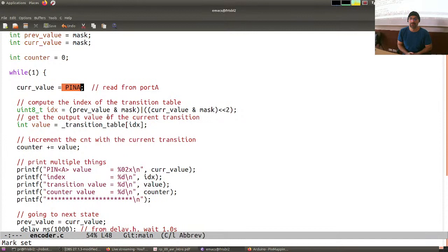Now, I don't like it because it involves a lot of ifs and a lot of branching in the code, first. Second, if you're going to implement this in VHDL, so on a real architecture, it requires a lot of ifs. And if is bad, because you have to say, oh, if this state is this, then do this. And then you have to do a lot of instructions to basically decide on which state you have to perform the transition.